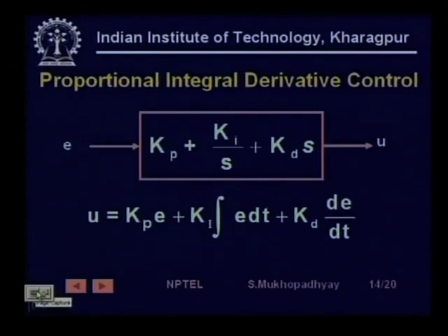One thing interesting to see is that we now calculate the input like this. Interestingly, you see that in the steady state the total E is 0. So, therefore, this term is 0. So, the proportional controller is 0, and since E is not changing, d/dt of E is also 0. So, that is also gone. So, we only have the whole output coming from the integral part. So, the 0 steady state error concept that we have studied for the integral control holds.